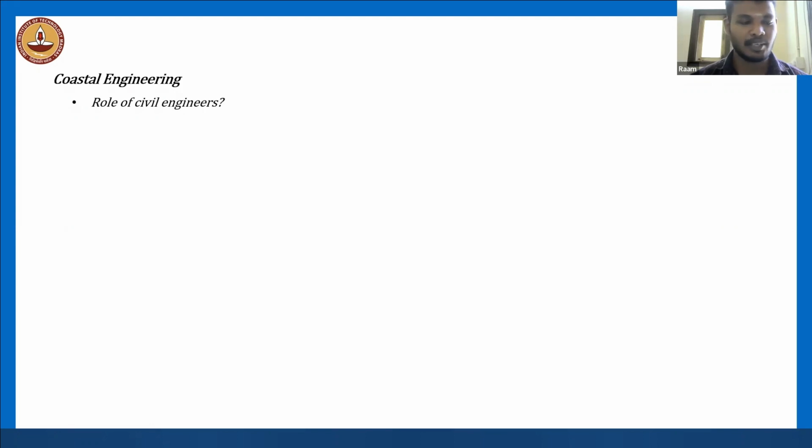part of our curriculum. In that type of structures, the additional loads which are calculated are hydrostatic load due to the standing column of water, and wave, tide, and currents. These are the various components which also have to be included. For that, we need to model the various component forces which are acting on the structures.